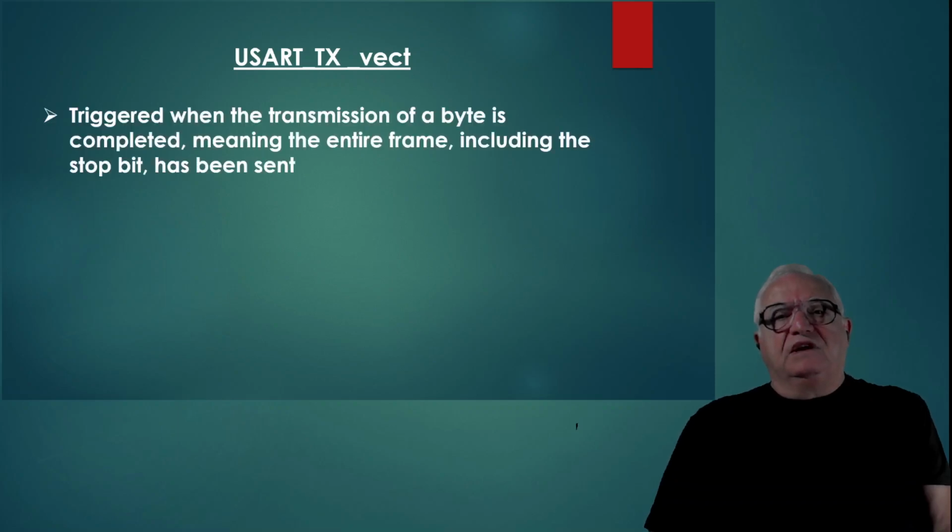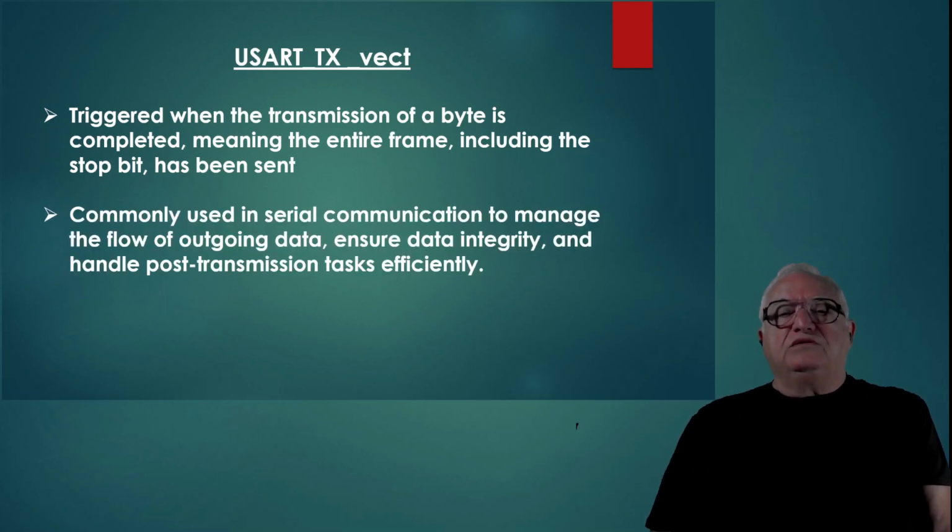UART transmit vector. Triggered when the transmission of a byte is completed, meaning the entire frame, including the stop bits, has been sent. Commonly used in serial communications to manage the flow of outgoing data, ensuring data integrity, and handle post-transmission tasks efficiently.